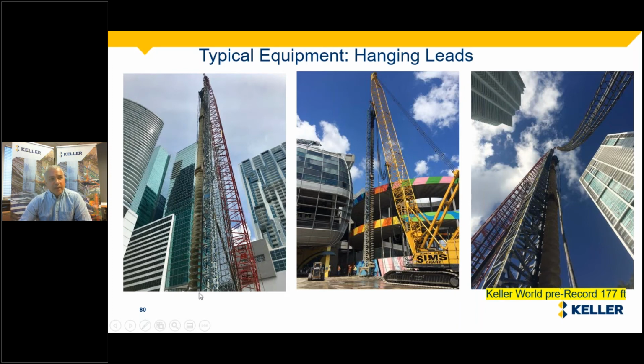It can also allow you to drill deeper piles because you can have a bigger crane. Normally, the fixed lead equipment is limited to about 30, 35 meters. There are new rigs, the Fundex, that can drill up to 50 meters, while the hanging leads have been able to get to 55 and 60 meters. We had a previous record of 177 feet, about 52, 53 meters. With this setting and with the attached lead, we were able to get 55 meters.